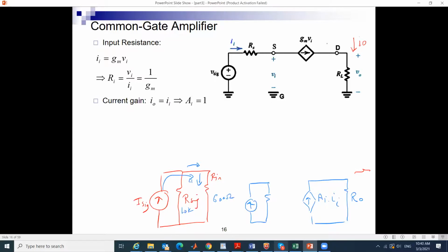To Rn, right? Okay, so Rn for this circuit, because from the gm it is very small, and so it has a small input resistance. It does not amplify well, but it can shield me from a supply whose signal resistance is high. Meaning I use it as a buffer stage.